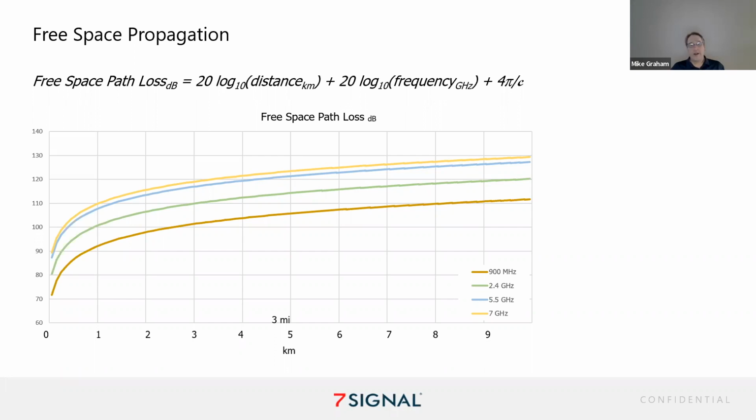I used to do a lot of point to points. And if you do it carefully, usually you can get within 2 or 3 dB of the predicted signal strength if you're using good, well-calibrated equipment. Plus or minus 3 dB is pretty good.